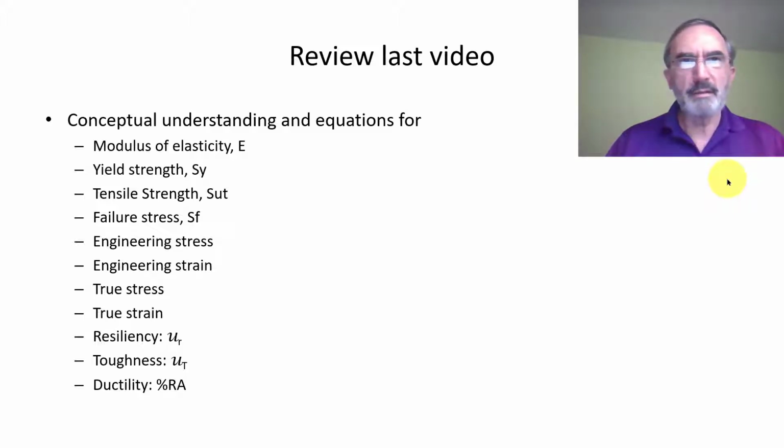Alright, so review from the last video. We accumulated a lot of knowledge from the last two videos. We have developed conceptual understanding and equations for modulus of elasticity, linear regression in Excel, yield strength, where the 0.2% parallel line intersects the curve, tensile strength S_UT, the maximum on the curve, and failure stress, that's a value at the end of the curve.